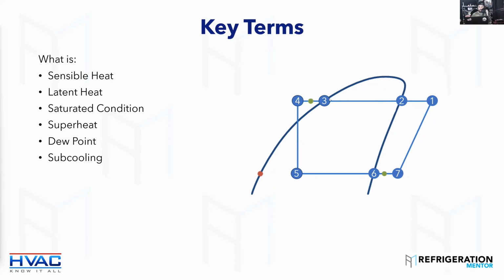Yep. So right here, you're 100% right, Ethan. So here's your condenser here. This is the outlet of your condenser. You should always have a high pressure, high temperature liquid leaving the outlet of that condenser. It should always be leaving your condenser as a liquid because you do not want flash gas in that liquid line. So it's always important to check your subcooling at the outlet. What else do we got here? So this is subcooling. Great job, Ethan.